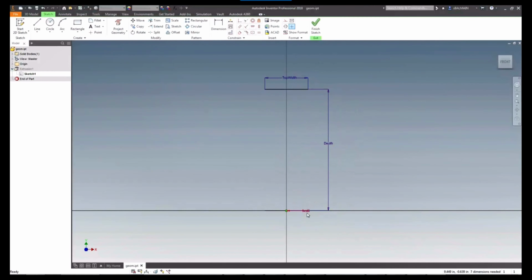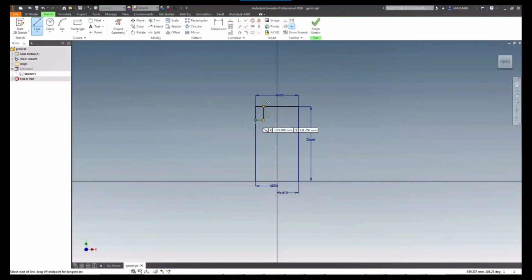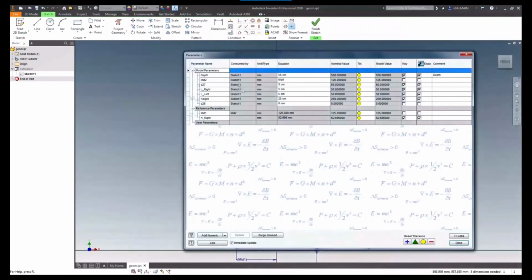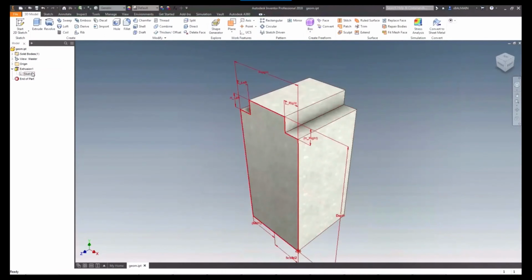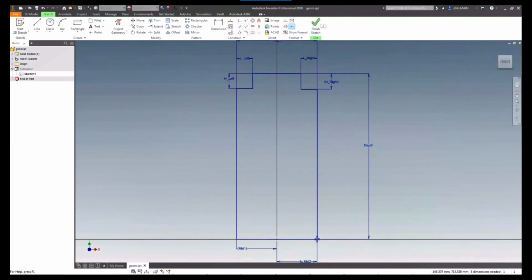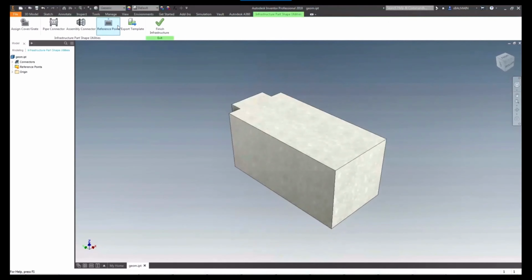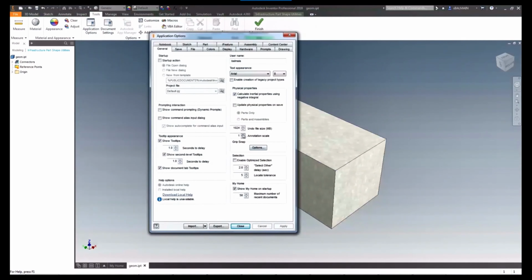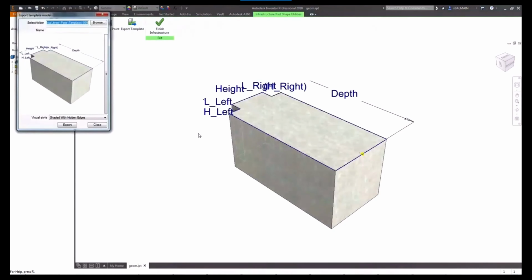After, I delete what is not needed and recreate the section I need. I change the units. And here there is a slab that will come at this point. So I create a void. After, I set my parameters, like this. And after, I use the infrastructure part shape utilities to save back in the correct format to be loaded in InfraWorks.